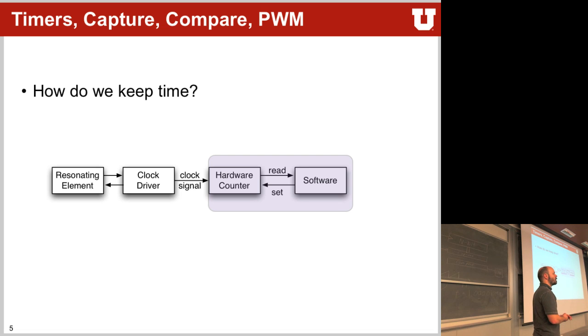Yes? Your CCR1 is flipping the bit, right? Yes, so CCR1 would flip the bit from 0 to 1, and then when you hit CCR0, it would flip it from 1 to 0. And how this all is implemented in the timers always depends on your manufacturer. So CCR1 and CCR0 is actually from the nomenclature that the MSP430's timers use.